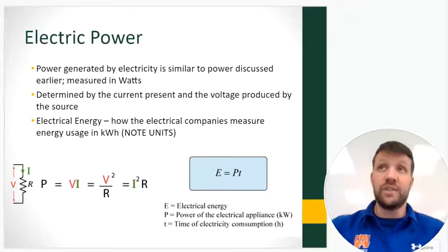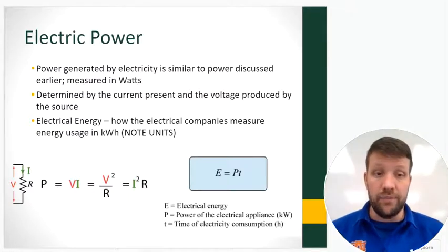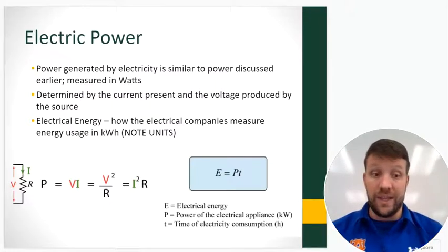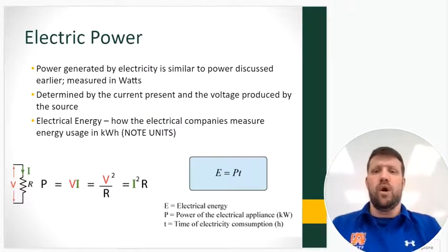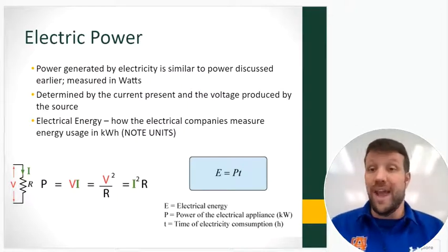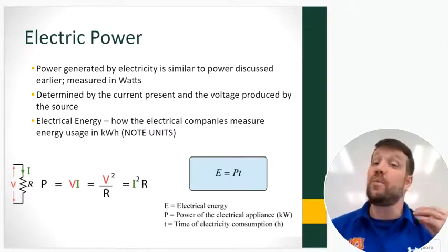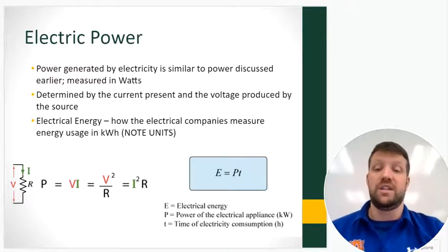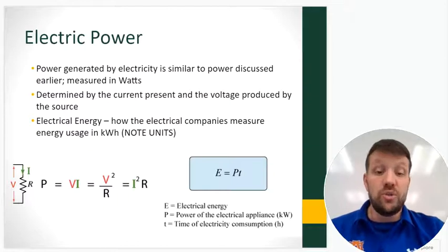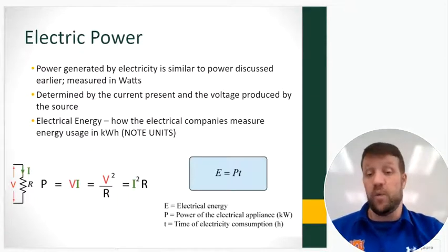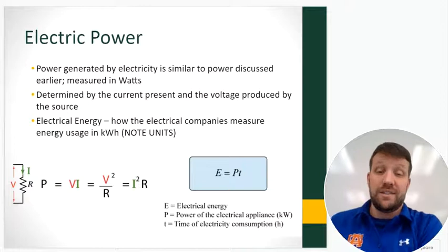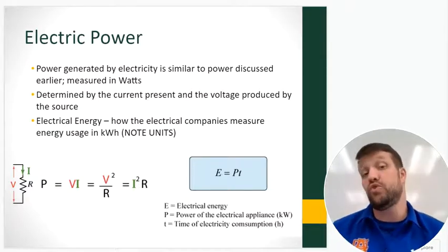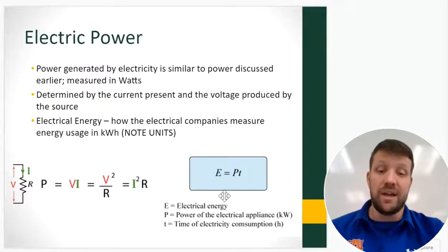Okay, well, if I turn that TV on, if I watch it for 2 minutes and I turn it off, and I don't turn it back on for a year, or if I power that light bulb for the entire year, I can't just say, well, one pulled more power and so it had to cost more to run. It's also about how long it runs for. Okay, so electrical energy companies charge using something known as kilowatt hours. And note that that's kilowatts, so thousands of watts in power, times the number of hours that you run something for. And you see that down here in the bottom right.